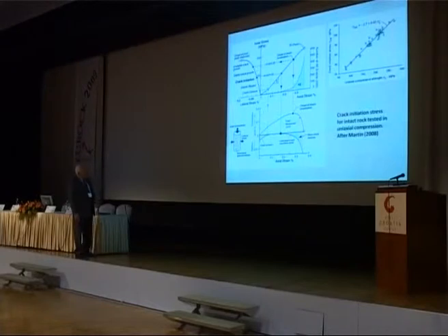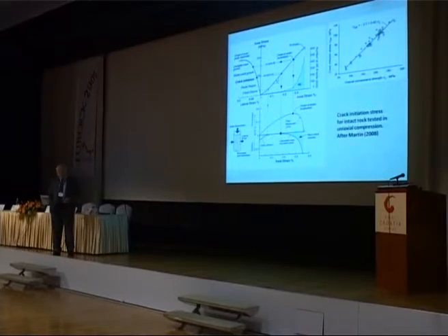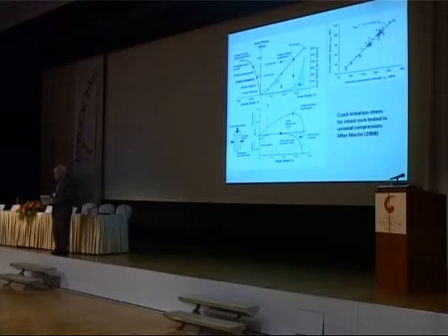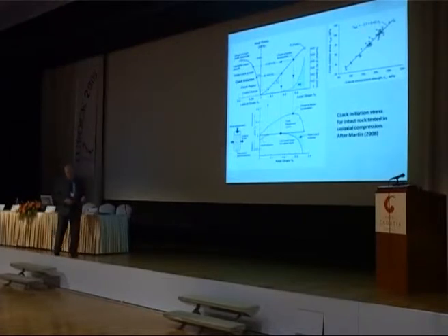Derek Martin has done a lot of work on the failure processes in particularly granite, and this is in relation to the Atomic Energy of Canada Underground Research Laboratory, where we had very good details on the rock material. It's a mass of granite, and the in situ stresses and the laboratory testing show that you have failure initiation at about 40% of the uniaxial compressive strength, determined either by acoustic emission measurements or strain measurements, and an increasing generation of cracks until about 70 to 80% of the uniaxial strength, which probably represents a reasonable estimation of the long-term strength of the material. And this applies for a great variety of rocks.